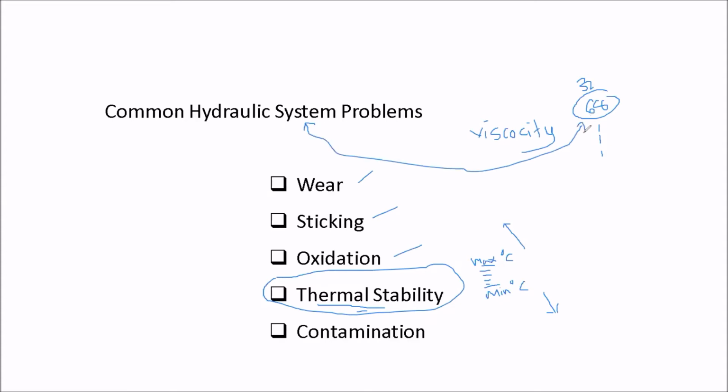If you say, for example, HLP 68, that means hydraulic oil 68. 32 is normally used in pneumatics. Remember last week I taught you about the pneumatic lubricator; the lubricator oil is size 32. So when you buy hydraulic oil, in most hydraulic systems they are using a viscosity of 68, the thickness of the oil.